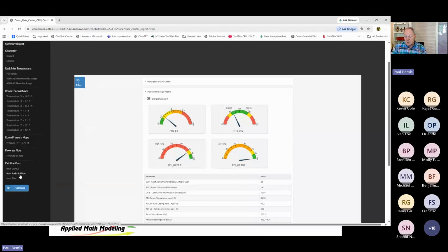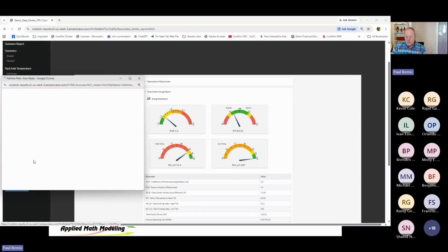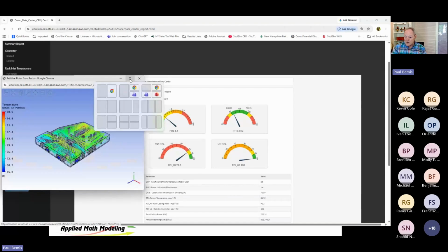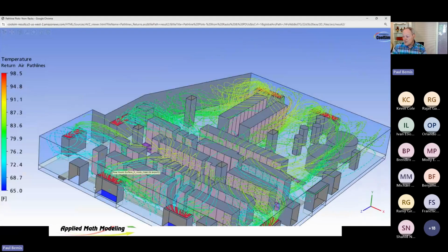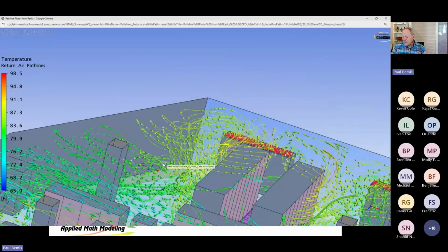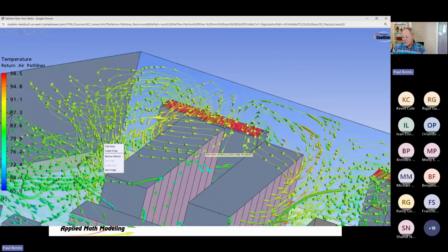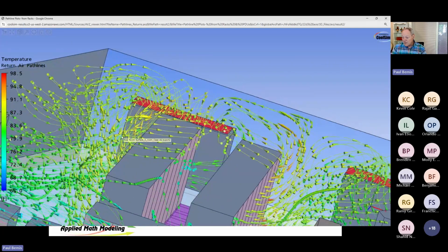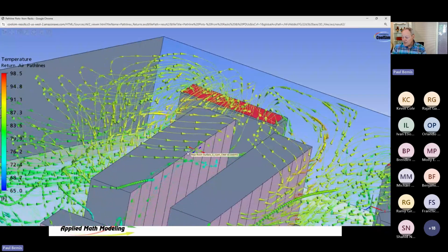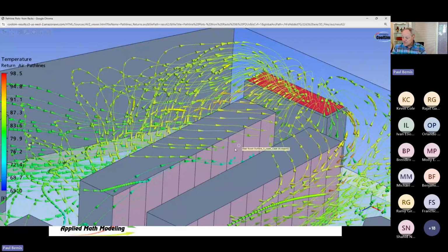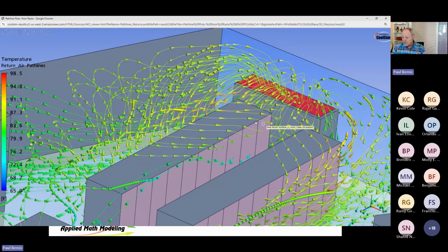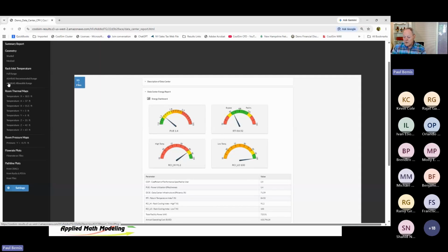We can look at path lines from the cooling unit, from the racks, and you'll see these are starting to recirculate on themselves up here. So you see what's happening is now I'm having recirculation airflow. It's going up over the rack and back into the inlet. You can see these inlets are pulling air in. So if this is a temperature range, we're at the 80-degree range, and it's pulling it right in over the top. And that's what causes this picture to occur.